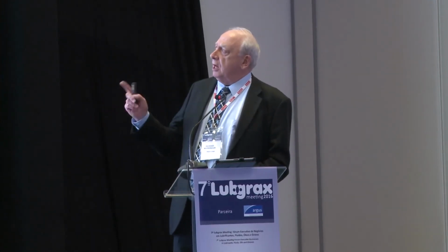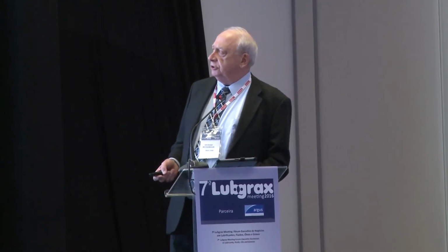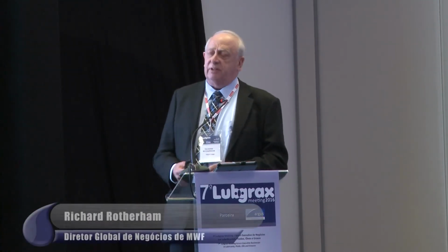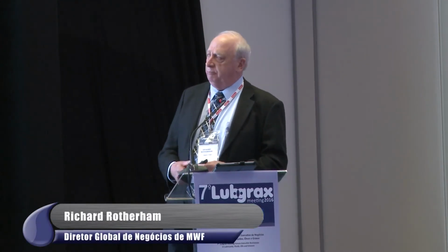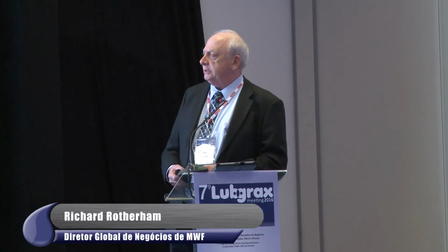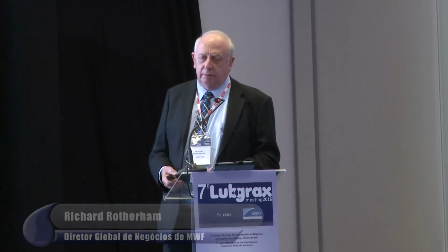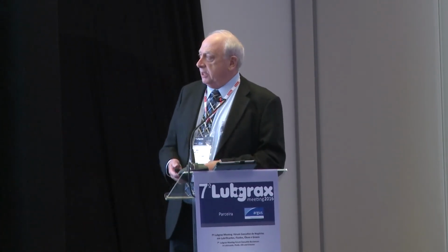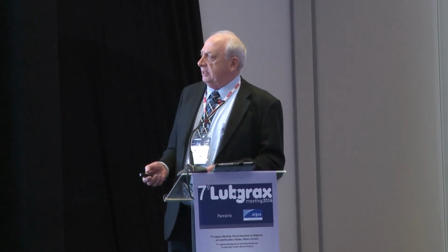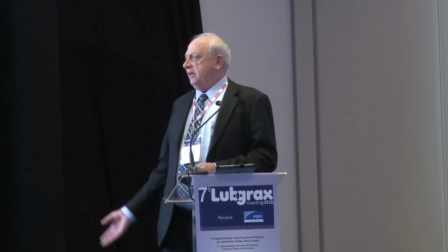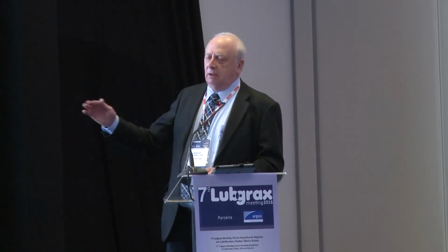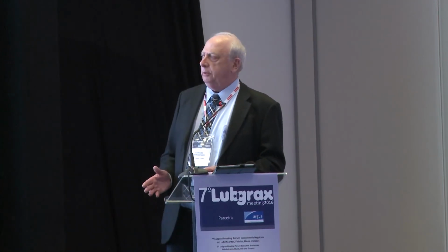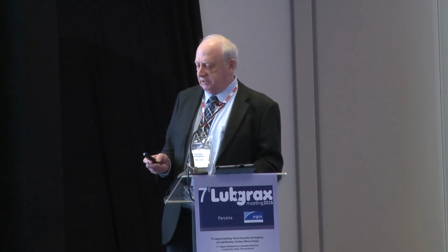In terms of monitoring biocides, concentrations can typically be monitored by things like HPLC. For some biocides, there are fairly simple colorimetric methods that can even be used by the customer in the plant. And at the end of the day, the biocide manufacturers and you supplying your customers are resources, so please use them. And obviously, every time you add fresh concentrate, you're also adding more biocide. So the amount and frequency of makeup will have a significant influence on the need for tank-side treatment.